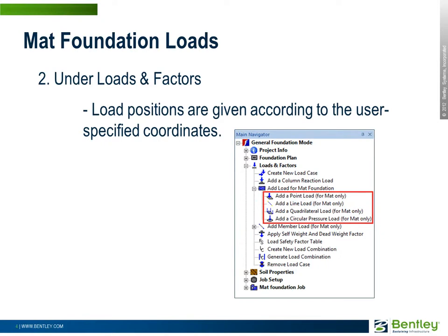The second method to add mat-specific loads is by selecting the desired load under Loads and Factors in the main navigator. Load positions are given according to the user's specified coordinates. I will briefly go over creating all four types using this method.